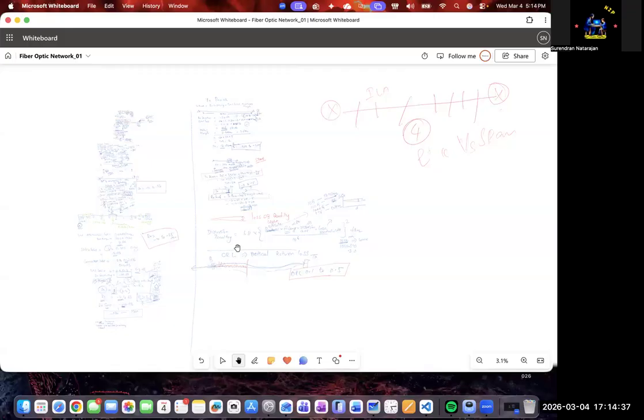I'm a little bit confused. Where did you get confused? The fiber only bears -5 to +5 dB. Yes, it ranges from there. Why don't we take +5 and just send it? By default you want to pump full power.